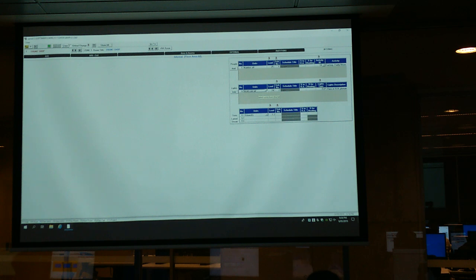And the schedule number, you remember in the project, the second one, schedule, for the time, corresponds to the number there. Then you can choose the total kilowatts or watts per meter squared. And you also need to choose what kind of lights. Different lights will cause different loads.